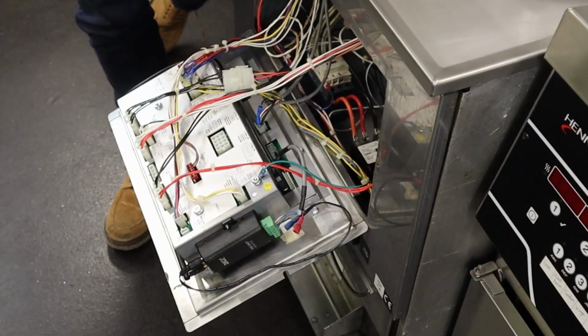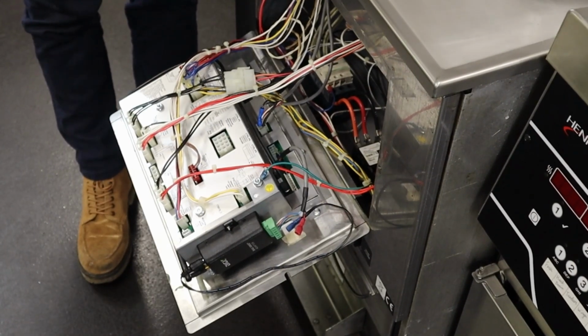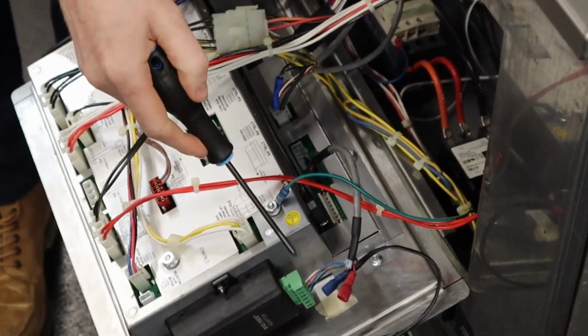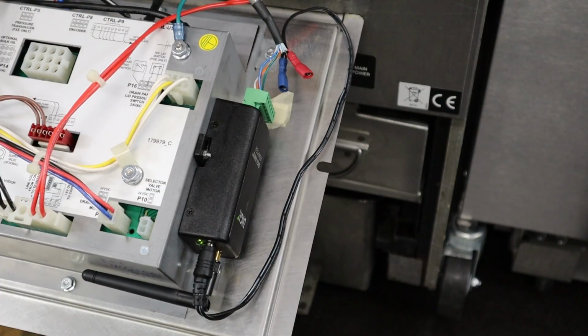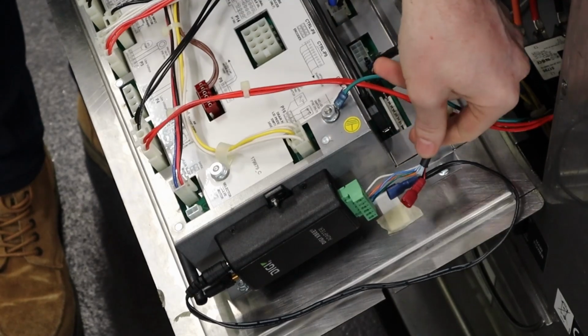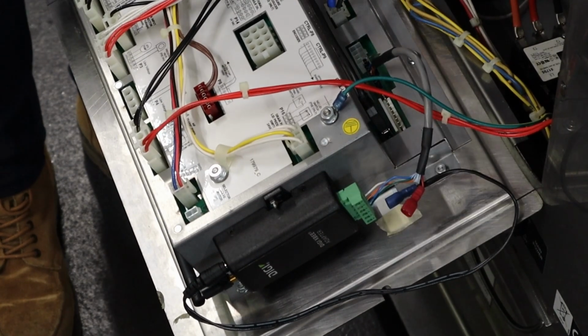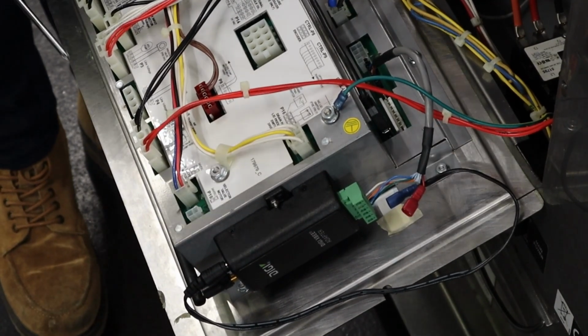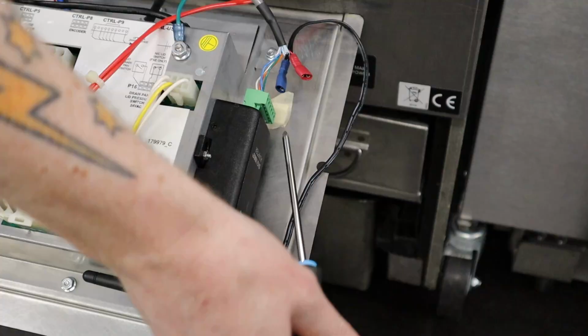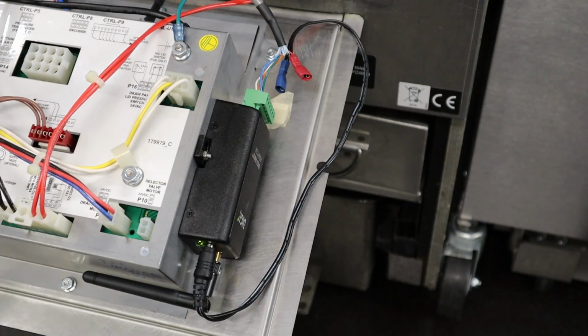correctly. Now, the other things that we might want to check on the radio is we've got our connections here from the radio itself to the controller. We might want to just check that our wiring there is in place and is locked in. So you might want to give the wires there just a little tug, make sure they're in place. If they're not, let's just get them back in, tighten them up using the screw locks on the side.